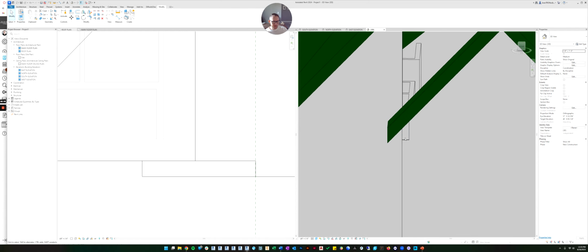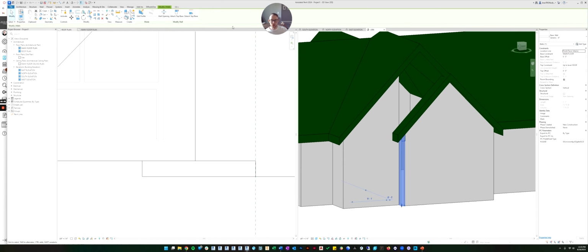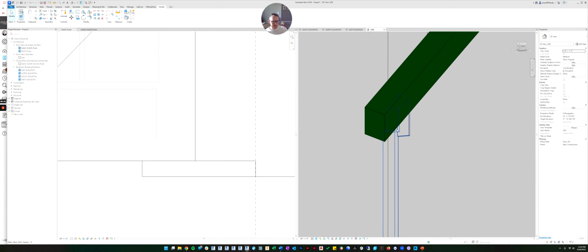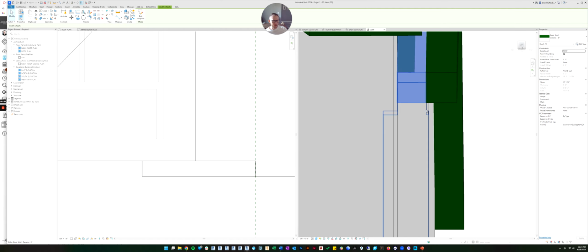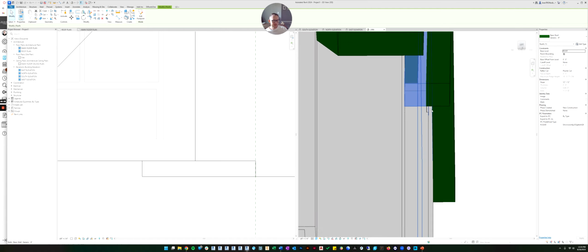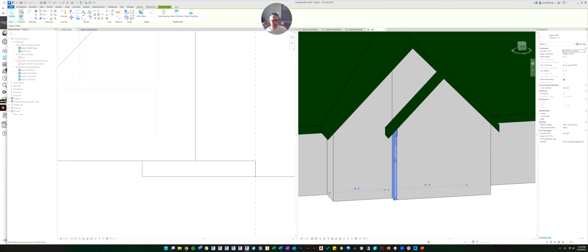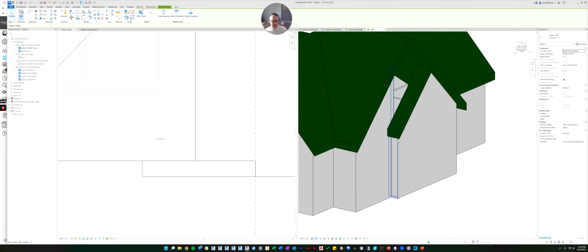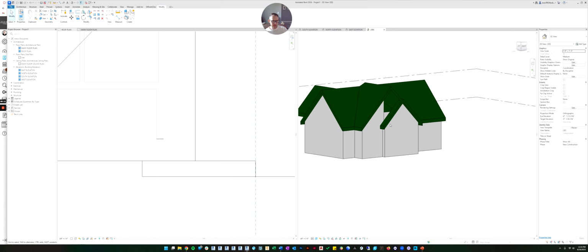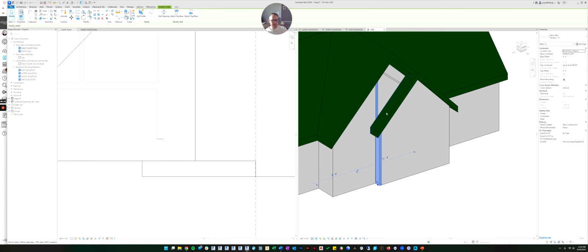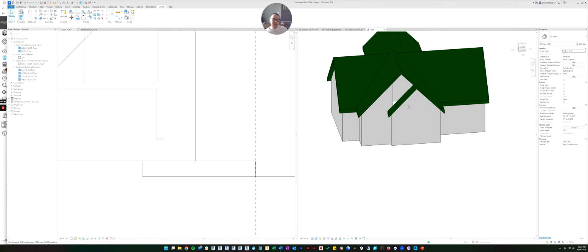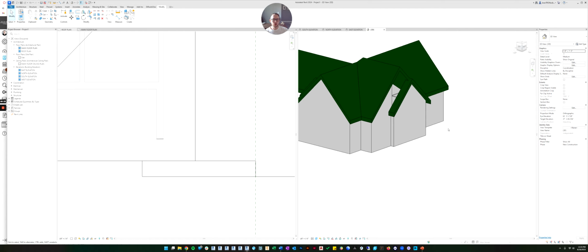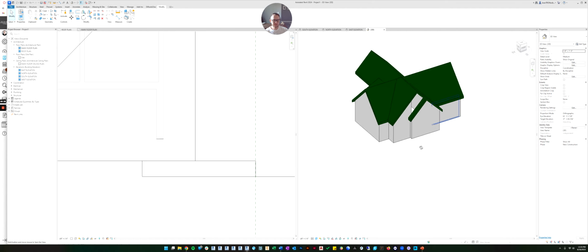We've got a little bit of a problem here because we also want to attach. What it's doing is it's attaching this wall to this roof, but that roof stops a little bit short of where the wall goes. So it looks like we also need to fix that little weird thing going on there. We also need to attach that to this big roof, like that. So that fixes it. That wall needed to be joined to both the little piece and the big piece in order to solve the problem. It can be a little bit finicky, and these are things you have to play with when you're working on your own because they can get frustrating.